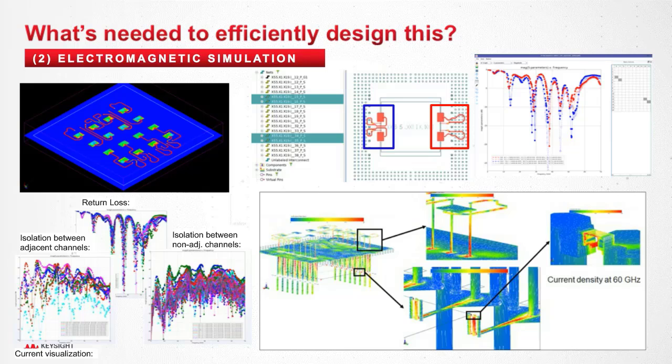And then on the bottom, we're also talking about potentially current density, so power integrity types of problems, where is too much current going through these really small vias, and also really looking at how the circuit is performing. So all of these feed networks are going to come together. It's sort of a rat race combiner with all these different antennas, and it's very challenging.